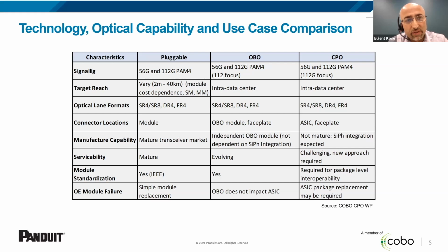But for pluggables, I just put heavier IEEE, but we can talk about Fiber Channel MSAs for the standardization as well. For the reliability, the module failure, pluggables is of course easy to replace, and for the CPO it will be very difficult to replace, and a complete module replacement might be required in that case.